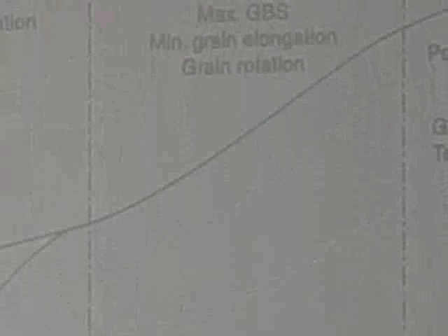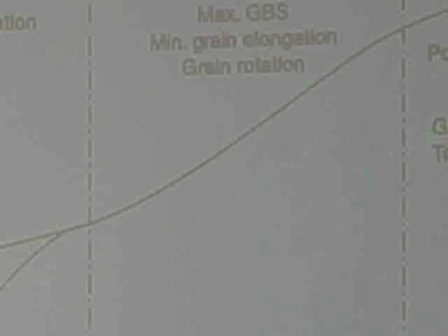This may be the best version I found. You can have diffusional creep, superplasticity, or power law creep, and this is the log of the stress. This is going to be a lower temperature, this is going to be an intermediate temperature, this is going to be a high temperature. Here you have, that should be 0.1 or 0.2, okay?